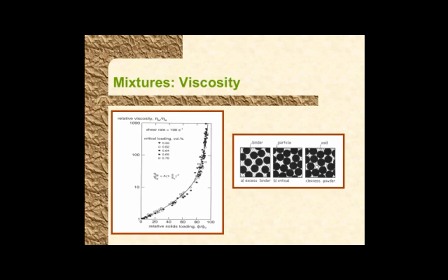So yeah, you can make the shape easily by having lower viscosity, but once you burn out the polymer or dissolve it off, what is holding the powder together? It's just powder-powder interactions, right? So the more powder there is, at that stage there's more strength in the shape before it sinters and bonds begin to develop.